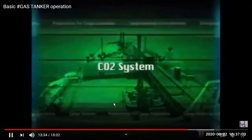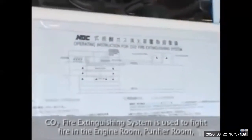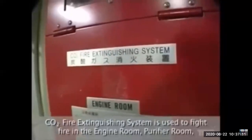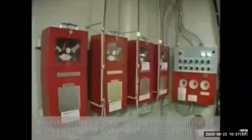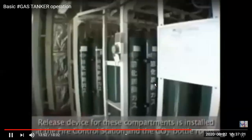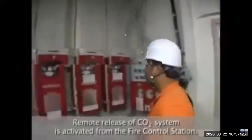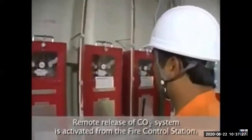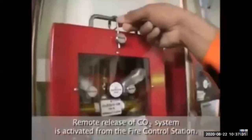Then we have the fixed CO2 system, which is there on most of the ships, same pipes like that. But here the fixed CO2 system is only used for the engine room or purifier room. The same can be operated with pilot bottles like this. Pilot bottles are there in the fire control station or the CO2 bottle room. So we open the box for whichever area and bottles we need.